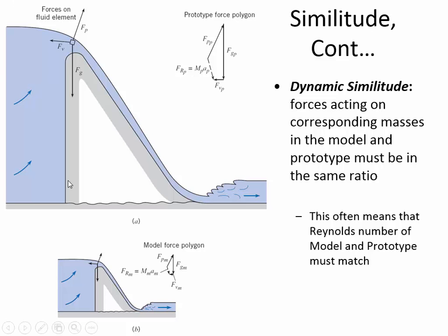This is basically looking like a dam, and the water flowing over the face of a dam is called a spillway. It's a kind of dangerous situation because the water gets so much velocity as it's falling downward over the face of the dam that the flow can become what's called supercritical, and then when it reaches downstream at the end of the spillway, it has to jump back up to a subcritical depth. So there's a lot of turbulence and a lot of energy gets exerted here in a hydraulic jump.